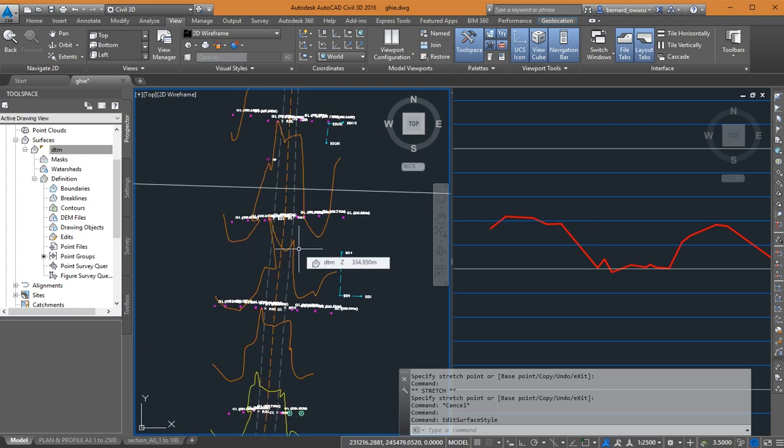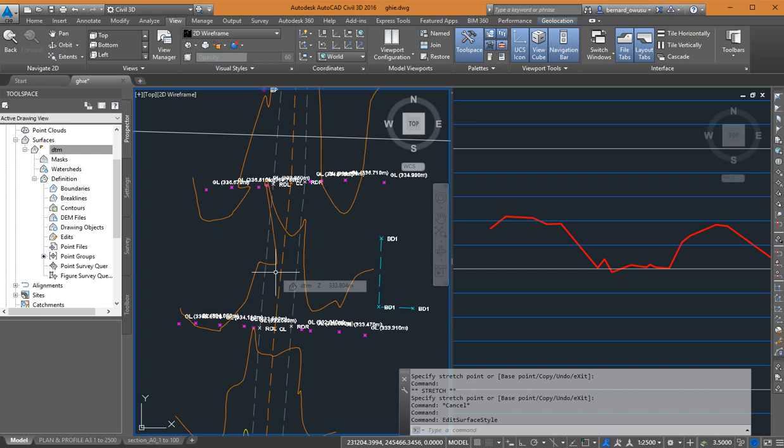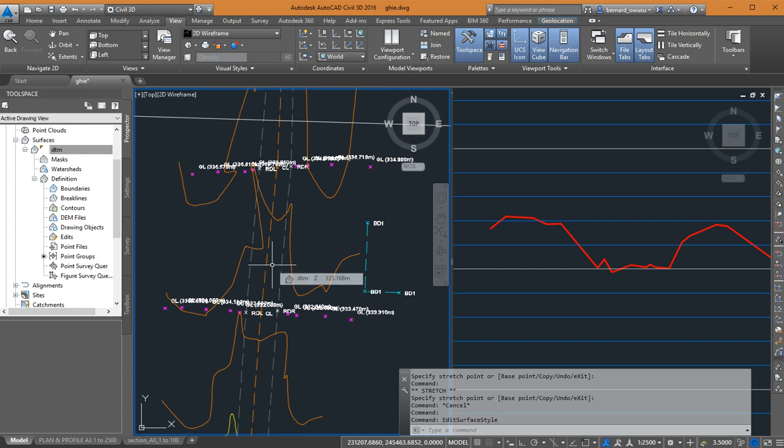Please, do you all have it? Okay, so quickly let's add the road edges as break lines. Then we also try and label the contours and see if we can change the contour intervals. Then we'll be through with the surface. There are so many things we can do with the surface. Maybe tomorrow, as a recap, we'll see where we ended and build upon it. Please, are we okay? Very good.